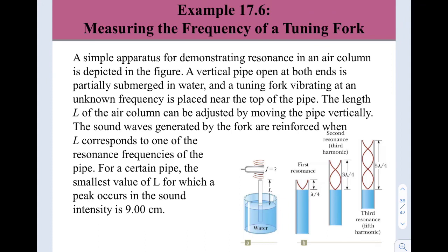So as we know, for this pattern, we are going to have a pipe closed at one end. Here there is going to be an antinode for pressure, which is a node for the displacement wave. For the pipe closed at one end, the total length is equivalent to lambda over 4 because of the shape here.